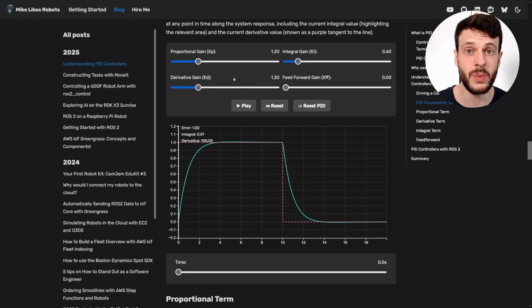Also, there's an issue with derivative gain, which is that because it acts on the error between 2 subsequent points, if you have a lot of noise in your sensor, so it jumps up or down sharply when the real value doesn't account for that, it's just the sensor being noisy, that can give you a much bigger response than you expect, meaning the controller doesn't behave very well. So try and keep derivative gains small because it makes the system more sensitive to noise.